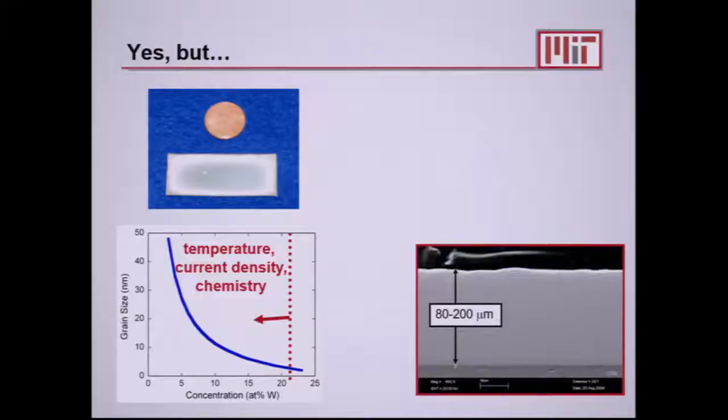And you know, okay, I'm no expert on electrodeposition, Andy, but there's all these knobs you can turn. You can change the pH and the chemical loading, and you can change the temperature, and you can change the current you're using. Go change variables, right? Go do something. It's not good enough to make one coating. We want to cover this entire range. And Andy said, I already tried those things. I already did 10 experiments. And in fact, in the literature, people have done that too. And here's the bad news. None of those work. There's a very narrow sweet spot for processing, and it's right here.